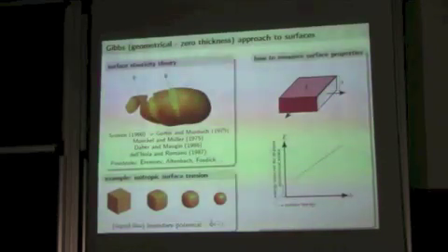But if you look at solids, you also talk about a different structure of the surface energy. For a fluid, surface tension is just one parameter. Let's call it gamma hat. For solids, you would also have some additional solid-like surface parameters. In order to calculate that, this is the experiment people actually do in atomistic calculations. You take this block, you apply periodic boundary conditions on these two sides, so it is sort of infinitely long. And then on top and the bottom, you break the bonds. And you apply a deformation to it, and look at the energy.